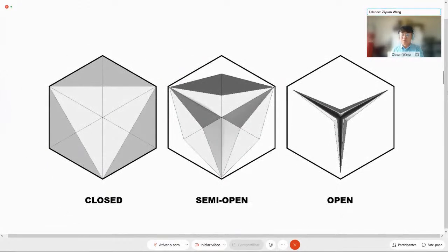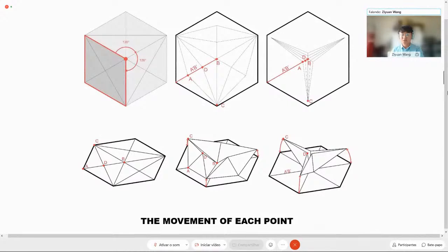First of all, the adaptive facade is dynamic. So to fulfill this kind of adaptive unit, we need to know the way it moves and preset the track for it. For better description, we rename each node as the letters A, B, C, and D. We can see that the entire component is regular, so rotating a diamond-shaped geometry by 120 degrees and 240 degrees, we can get a regular hexagonal geometry.